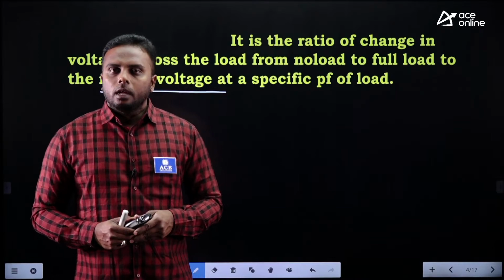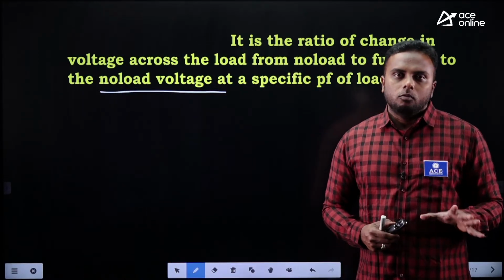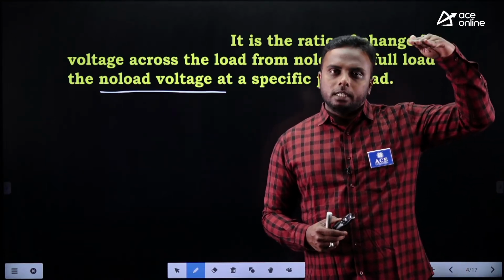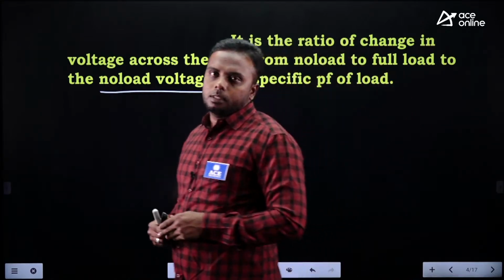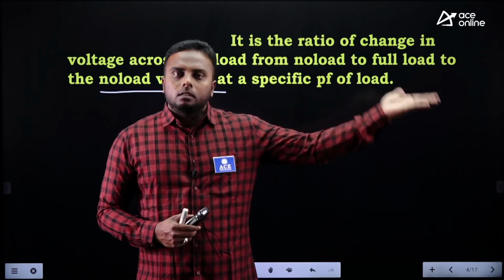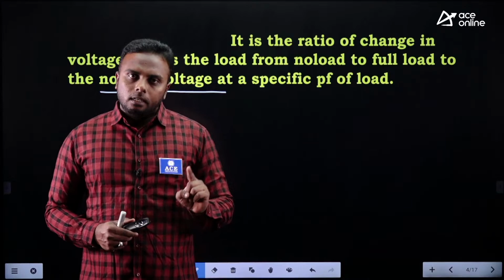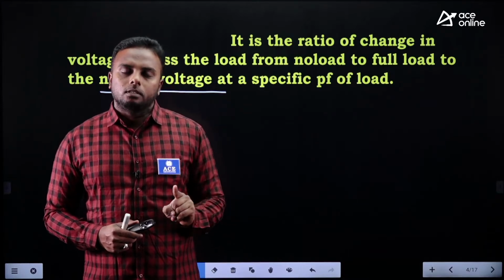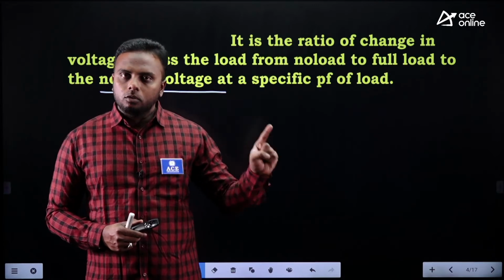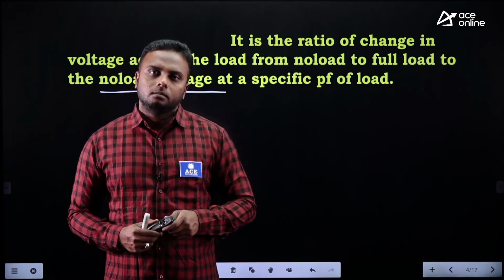Whenever there are lagging power factor loads, regulation will be positive. Voltage drop will be there, so we do tap up there. Tap up means some turns we increase. Whenever turns increase, automatically voltage rating will increase. Then load voltage will be maintained properly. So it is very important to know practically the voltage regulation of transformers, so that a proper voltage can be maintained at the loads by using tap changers.